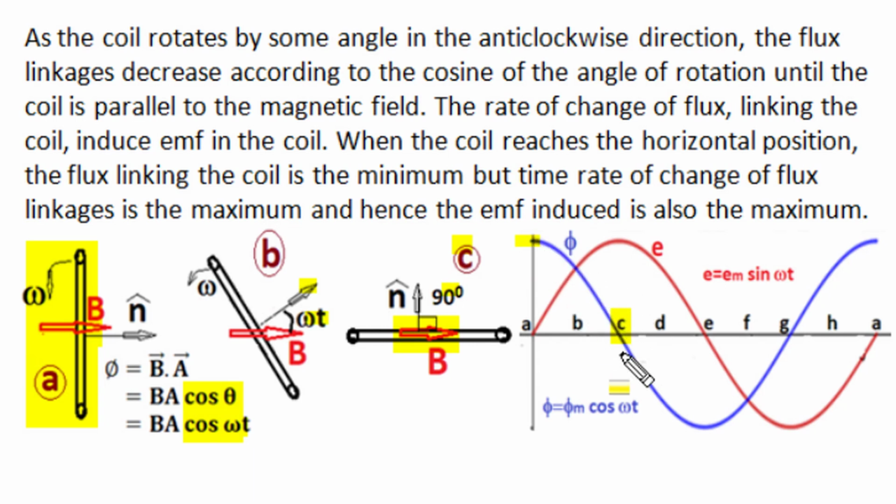near C position the rate of change of flux linkages with respect to time increases in magnitude, and accordingly, as per Faraday's law of electromagnetic induction, the induced EMF, which is directly proportional to the rate of change of flux linkages, is initially 0 at A position with maximum flux linkages, as shown in the red curve. As flux decreases, induced EMF increases, and in C position, when the flux linking to the rectangular loop is 0 but the rate of change is maximum, the induced EMF in this C position is maximum.